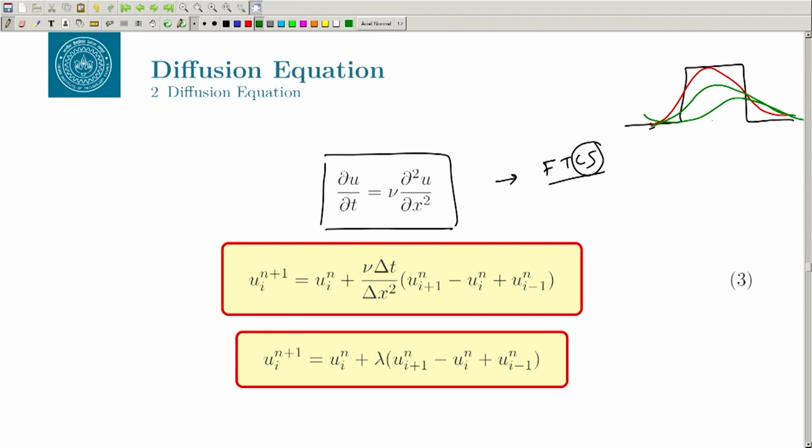So, you can use the value which is positive and also negative. So, you can use the central differencing in this case, and your scheme will still be stable. In fact, you should use central differencing in this particular case, because central differencing is more accurate.